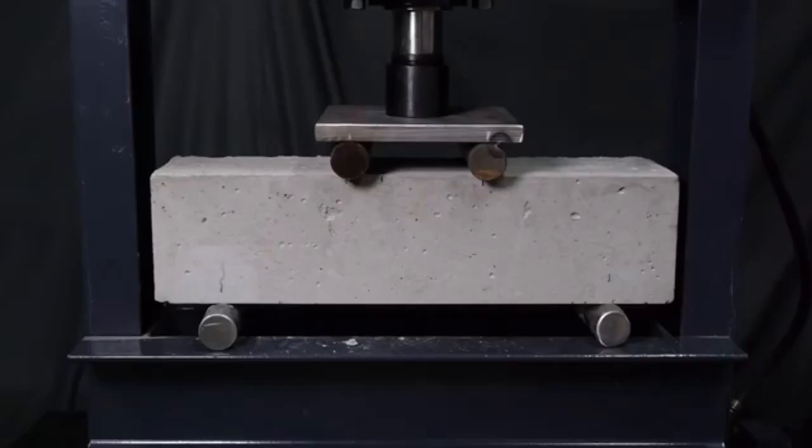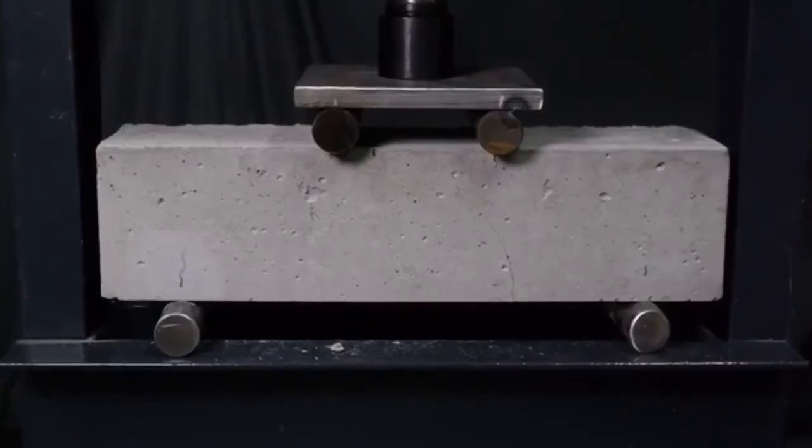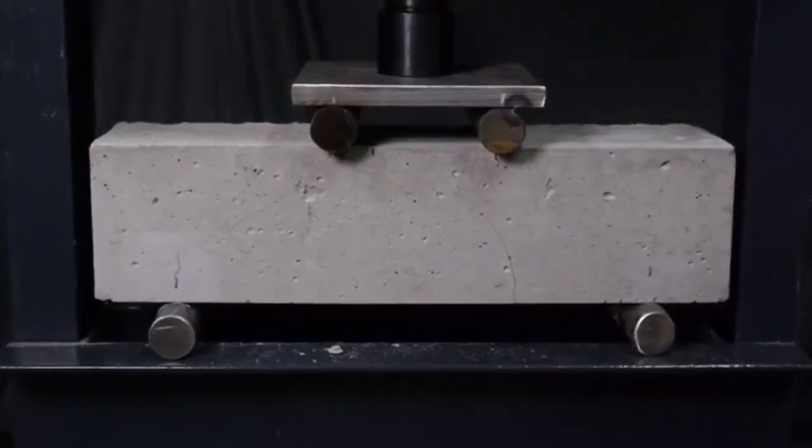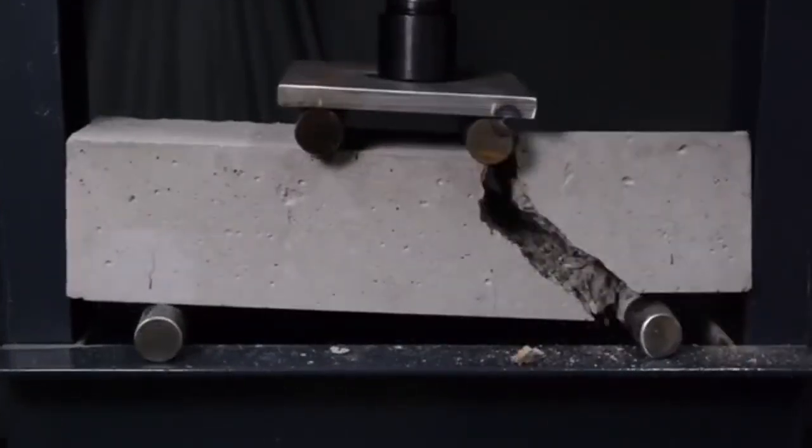of the member. This demonstration is from a test in a previous video showing a conventionally reinforced concrete beam. Go back and check out that video if you haven't seen it yet. Notice how the beam is resisting the load on it even though it's cracked at the bottom. It's meeting design criteria number 1, it's holding the load, in this case 6 tons, without failing. But it's not meeting design criteria number 2, serviceability. It's deflecting too much, and the concrete is cracked. Those cracks not only look bad, but in an actual structure they could allow water and contaminants into contact with the reinforcement, eventually causing it to corrode, weaken, and even fail.